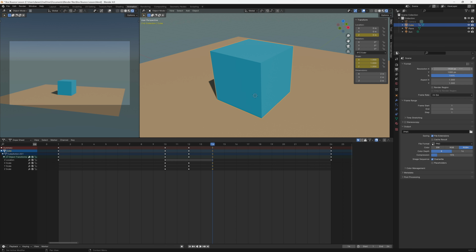But for now, we're just going to leave everything as default. Percentage 100 because you want the full HD to be rendered. Don't mess with aspect ratio. Frame rate's 24. Start and end is 24 because we're just going to watch this loop repeatedly. What's important now is here where it says output. First we want to make sure this will be saved somewhere. You can use your OneDrive or just the desktop, then transfer it to OneDrive so you can easily find it.